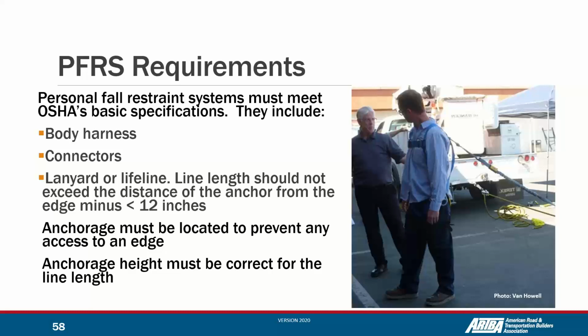Then the other category is the engineering control methods, which is how we can design the work zone in a way in which we can protect and prevent accidents, especially if we can design a place in which we use guardrails, for example. We can install the guardrails, we create this protection for our workers, but these guardrails are not always practical because in some circumstances we cannot use guardrails. In some circumstances, we cannot use a net. We need to use personal protective equipment that we need to train our workers how to use, maintain, and identify if there is any deficiency.